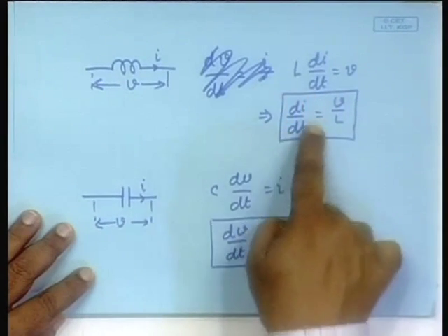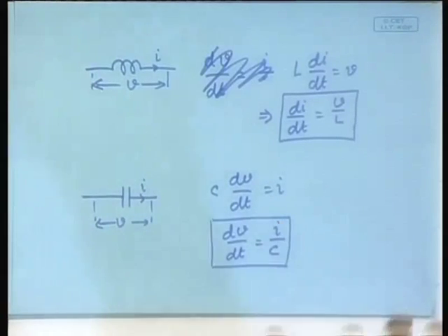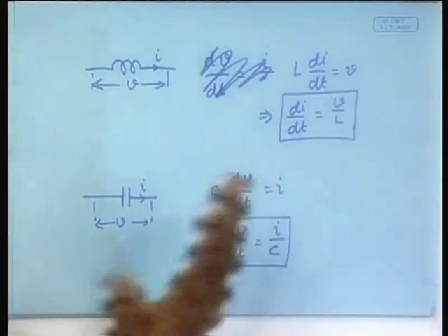We have understood that the right way of choosing the variables would be to say that the current through an inductor is a variable and the voltage across a capacitor is a variable, right. Why? Because of these two, current through the inductor, voltage across capacitor, these are the minimum variables necessary. So, we will say the current through the inductor and the voltage across the capacitors are the variables.